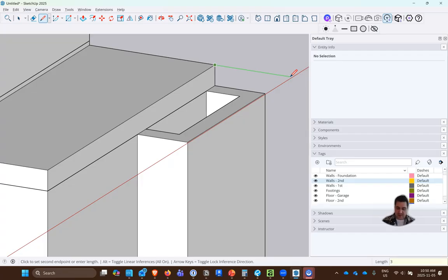If we use our math last time, we used 11 inches for the run. So let's go out 11 inches. So 3 times 11 would be 33 inches. And then we're going to go down 7 inches times 3. There's probably actually a more exact number for that, but we got 21 inches down.